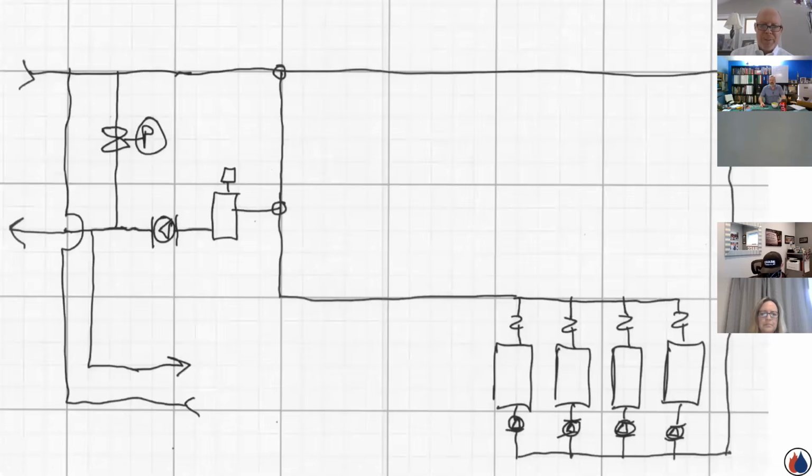And literally, if you just did a hand sketch, what we have is the boiler loop, 4 boilers with their own pumps, flow control valves injecting into this loop here. We have a distribution pump that's feeding the entire building, so we'll get takeoffs going left and right. The returns are coming back, and here's my common pipe. So I'm either flowing in this direction, or if I am injecting some boiler flow, an equal amount is coming back from the system. So in fact, it was primary secondary, even though it looks different.